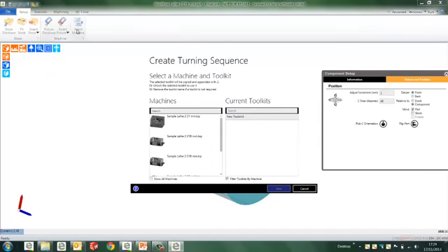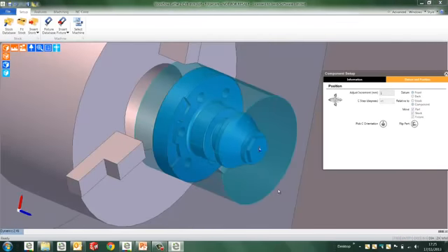Now we can load the part into the machine tool. Here I'm going to pick a sample machine tool from the installation of Edgecam. This is the place where we'd implement the custom post processors. Once we select the post processor, we're then offered a series of toolkits. This could be a representation of the job that's been pre-kitted, or indeed standard tools within the machine tool carousel. So once we've picked the kit, we can now move on to the next stage, which is the Features tab.